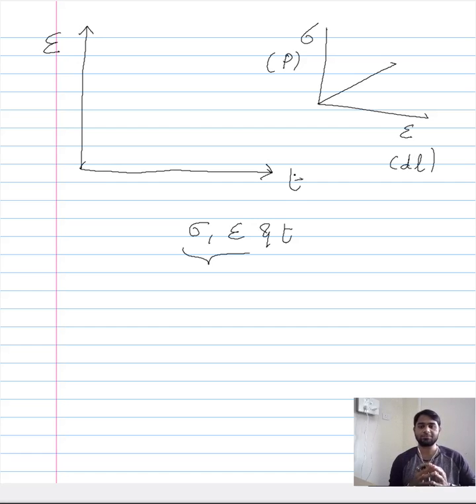In the case of anelastic curves we confine this strain to elastic strain, but since creep is not confined to the elastic region alone, this will be referred to as the creep strain here. Since in this lecture and the subsequent ones we will be focusing largely on creep, whenever I use this symbol epsilon, it means creep strain.